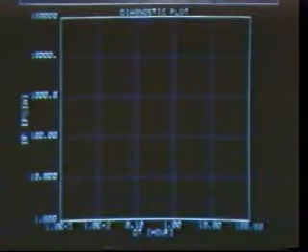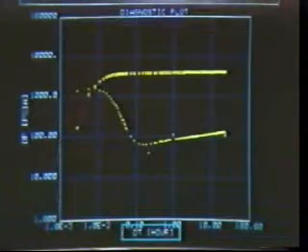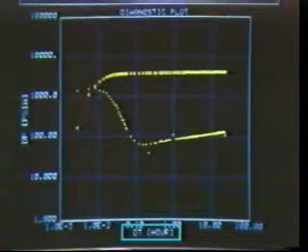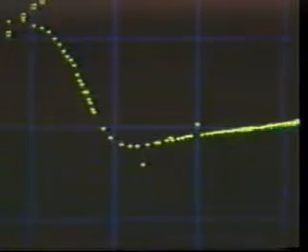As we've said elsewhere in the 400 series, the modern methods of well testing make use of all the data acquired during the course of a well test, including the data from early time. Modern methods graphically characterize the data by plotting it in the form of delta P, the change in pressure at the sand face, versus delta T, the elapsed test time, in log-log form. Additionally, the pressure derivative, with respect to time, is also computed and plotted on the same log-log plot.